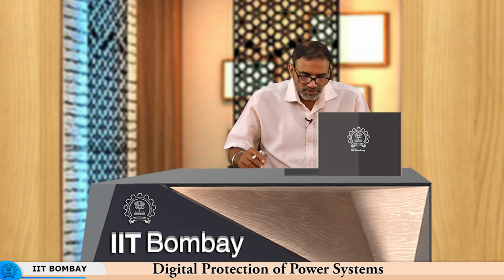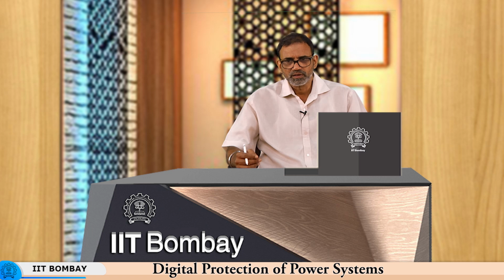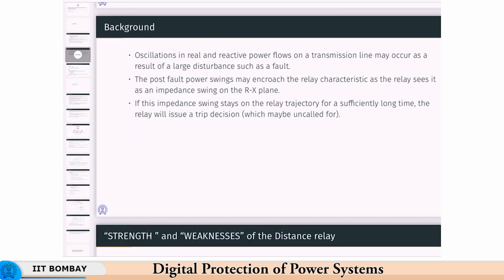Okay. But again, as we can see, this depends on carrying out multiple simulations and can be difficult to set. That is why, even though there are blinders and other power swing blocking techniques, they are successful many times when blackouts occur, but when they are unsuccessful, it can lead to unwanted tripping of important lines, and then lead to cascade tripping and blackouts.